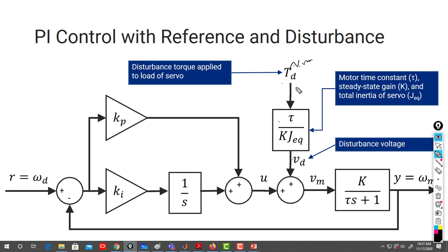If I ask you, so you apply Newton meter, so it reflects better than you apply, okay, I apply 0.3 volt, or I apply 3 volt. So what I asked you in one of your assignments for the DC motor adding disturbance, you applied, basically, what did you apply is not actually a torque, you applied a voltage because you injected it directly in this hub. Okay, if you want to apply something that reflects a Newton meter torque, so you need to add this block in your simulation. That's it, nothing more.